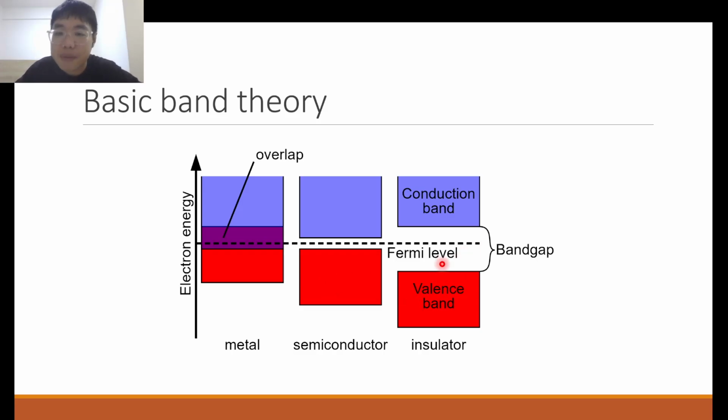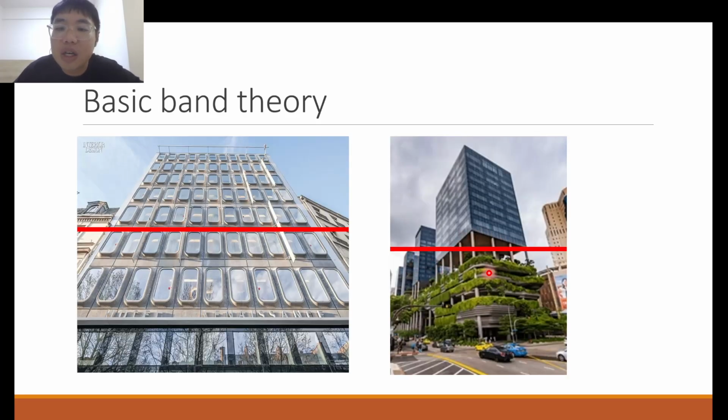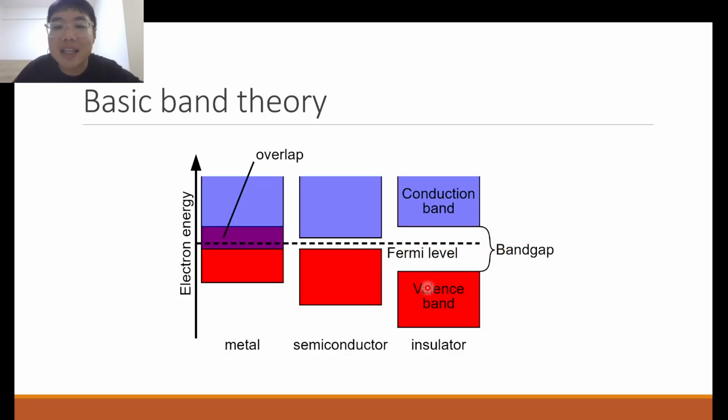You cannot move up to empty space, or move left or right, because the band gap, what we call the band gap, is devoid of spaces for electrons to move. So it's like just now the building here, no rooms. You cannot be dangling in mid-air, correct. So same thing here. The electrons cannot exist in any area in this region. So to move, it has to go up to the conduction band. And when I mean up, I mean higher up in energy, because the vertical axis over here is electron energy increasing upwards.